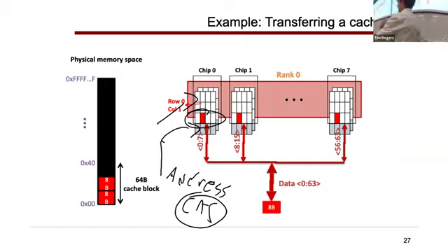Again, you can design this differently, but typically if you want to initiate parallel column and row address strobes, you need it to start sensing the output as quickly as possible. So each of these individual banks that are stacked on top of each other in this diagram would have their own row buffer, and you would be logically switching between those row buffers when you went to access different banks. Does that make sense?